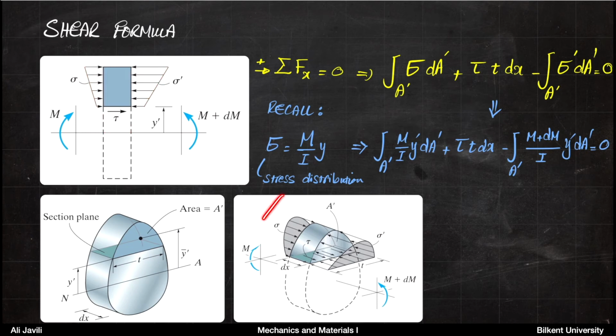So this is your relation for sigma, and what we want to do now is to replace the stresses using the flexure formula. Okay, so we do that. Pay attention that this formula before came with a minus sign to indicate that the stress here is compressive. But we don't have to do that. We already paid attention to the signs when we wrote the equations. Okay, so this would be now your equilibrium equation.